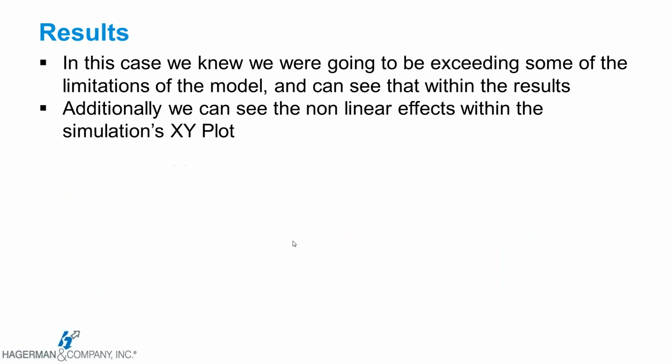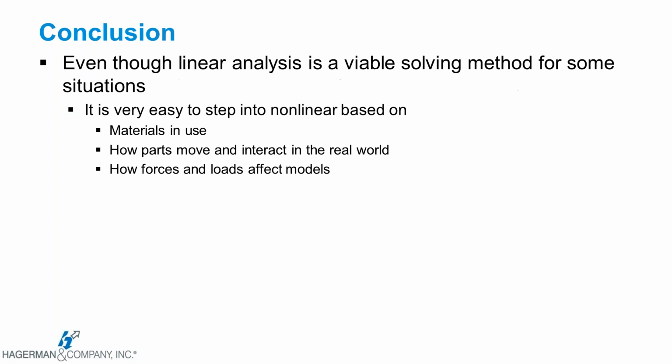So in this case, we knew we were going to exceed the limitations of the part, but we can see that within the results. And again, beyond that, we can see the nonlinear effects within the XY plot, within the deformation versus scale. So in conclusion, in linear analysis, don't discredit it. It has very high potential for simulating some real-world environments, but it's very easy to step into a nonlinear environment based on a number of factors, right?